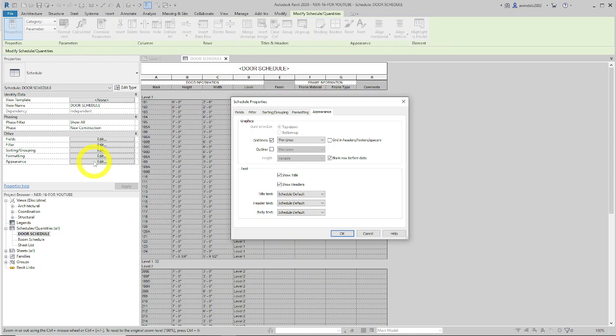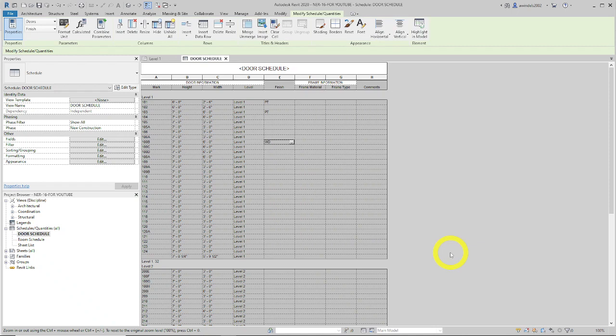This gets a little tricky. We're going to add a bunch of things similar to figure 16.13, and we're going to change some formatting of a few things. So the grid lines are going to stay thin. We're going to say outline around is going to go to medium lines, and we're going to keep these the same. We're just configuring the schedule's appearance, basically. That's all we're doing. We're doing more of how it looks like Excel style.